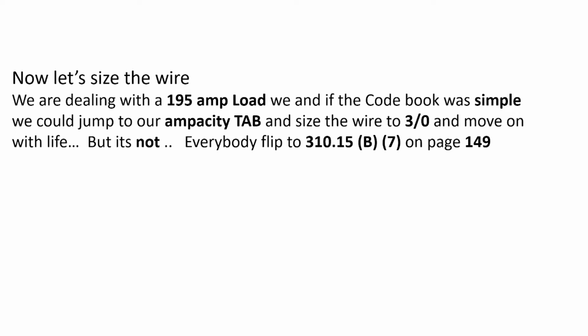Okay, and we're going to take a look at the top left-hand corner of page 149, and this is for single-phase dwelling services and feeders for one family dwellings and the individual units of two-family and multifamily dwellings. Service and feeder conductors that supply a single-phase 120-240 volt system can be permitted to be sized in accordance with 1 through 4.